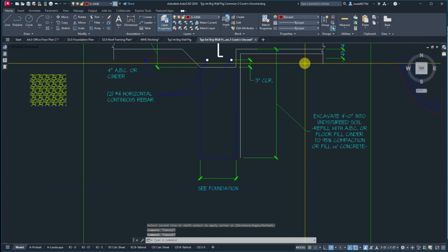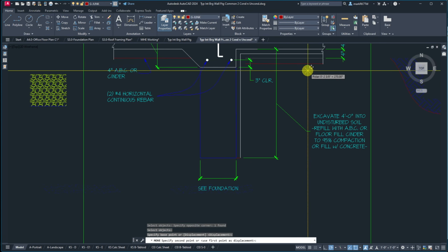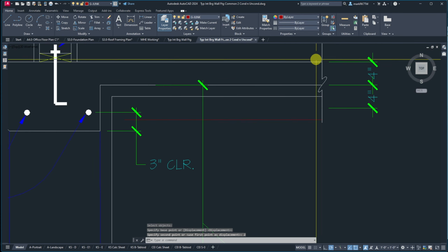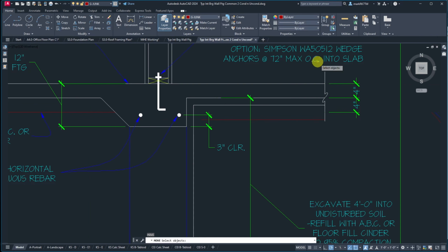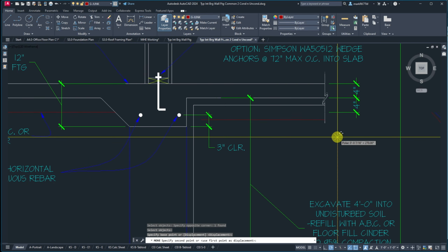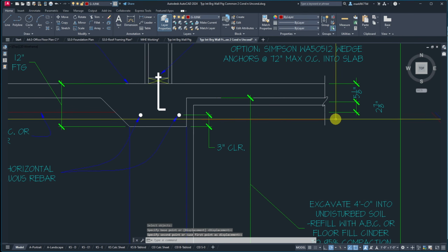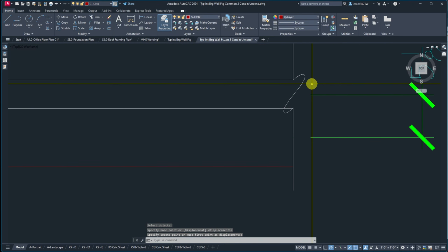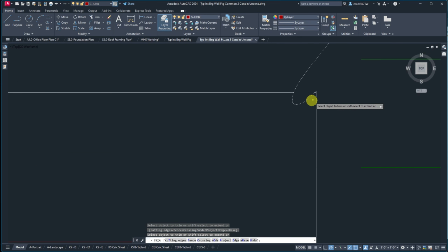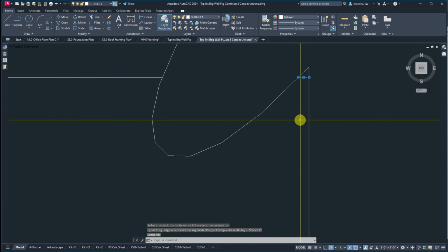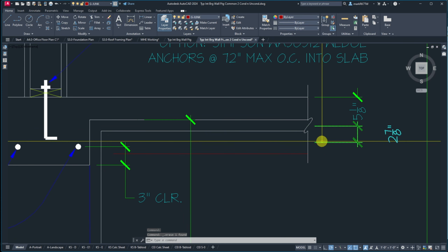And then this, now since I moved the insulation down 2 inches, I'm going to move my aggregate down 2 inches. And we're going to rehatch this, so if I want it to look a little more even, I can move my break line down to where I like it. Looks pretty good. So I might need to do a little trimming, like that guy. And I'm just going to trim back to here. I mean, you could leave that line, but it's just going to turn into a blob. So I'll get rid of it.